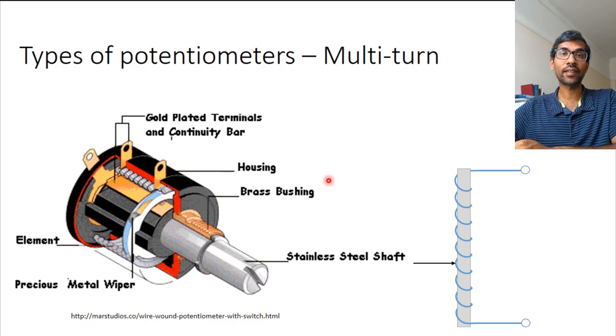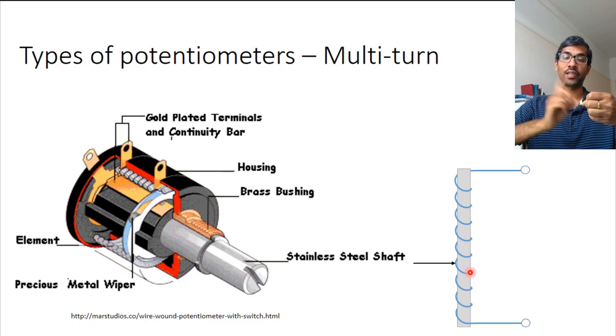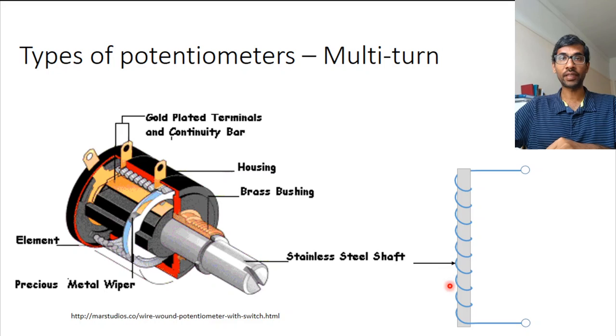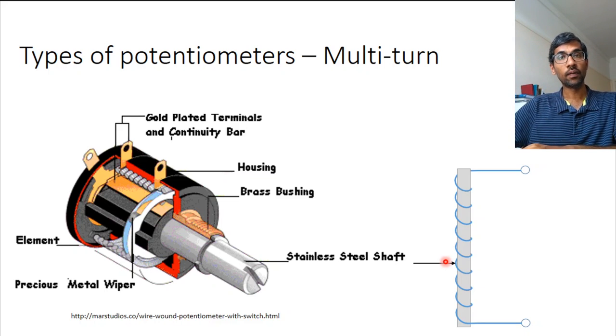And the way you do that is basically you take this linear displacement sensor that we already talked about, right? Which basically has a spool or a card, and there's wire wound about it, and this wiper moves up and down and makes a potentiometer. And what you do is you connect this wiper to a screw, so that as you rotate the screw, this wire moves up and down. And that's the idea here.